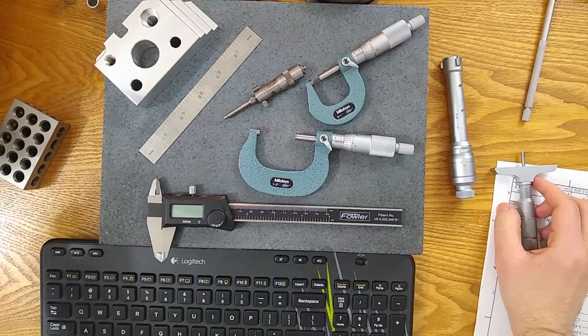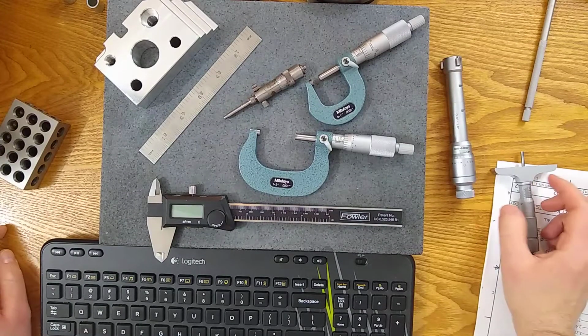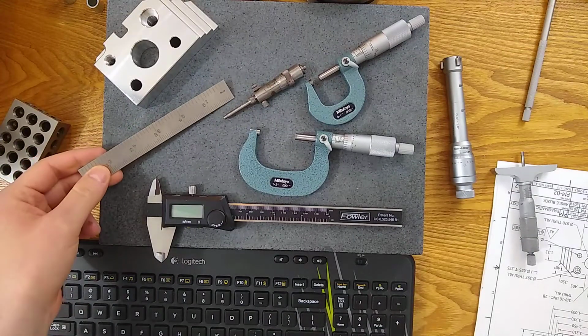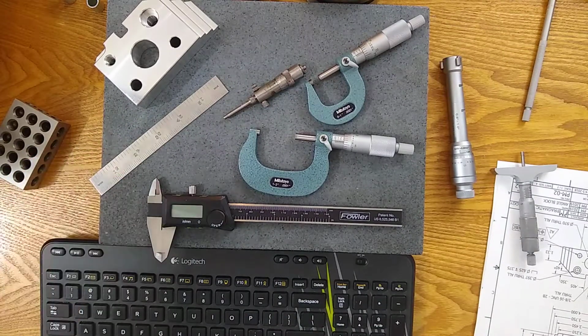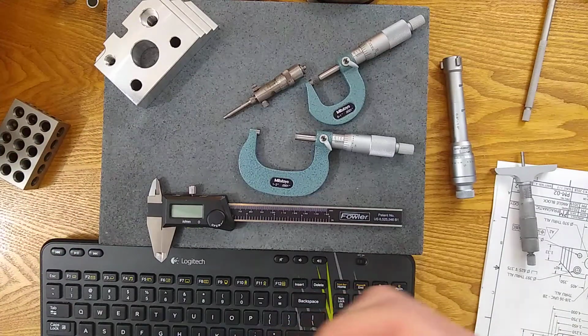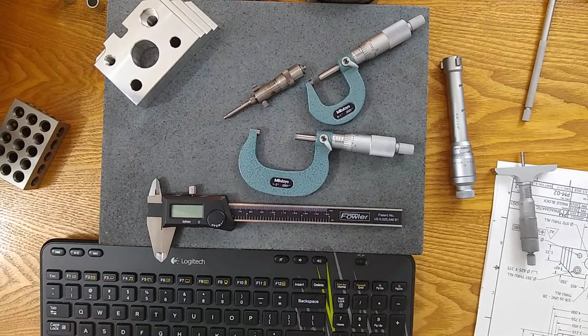Lesser gauges, in this series, I don't cover a whole lot of steel rule or tape measure. We do a little bit of feeler, radius, angle gauges. A lot of these are reference only. You can certainly calibrate these. You can certainly make these a part of your inspection process, but in many applications, they're used as a reference to check that manufacturing is doing things correctly. And so you gotta be aware of that.